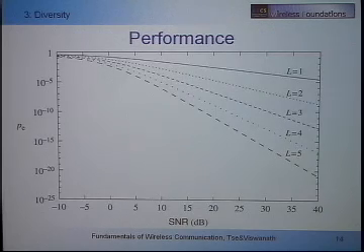So we plot the error probability curves. We see the improvement, okay? When L equals 1, we have this curve. As we improve L, this curve shifts down. The AWGN curve is somewhere here, the waterfall curve. And now we are closing the gap between the no diversity situation and the AWGN situation with time diversity. Okay?